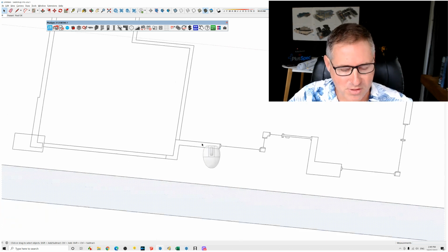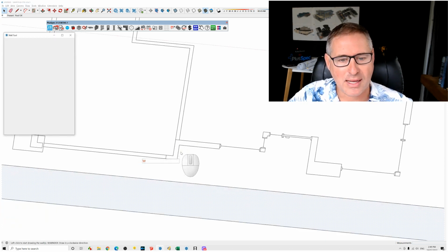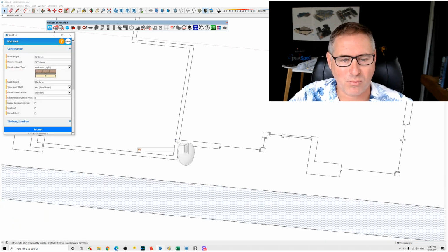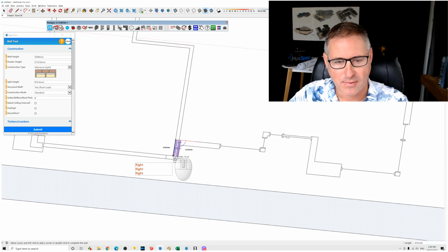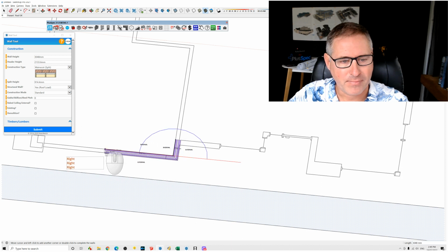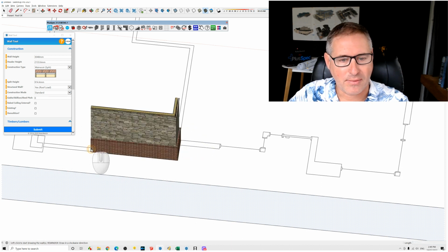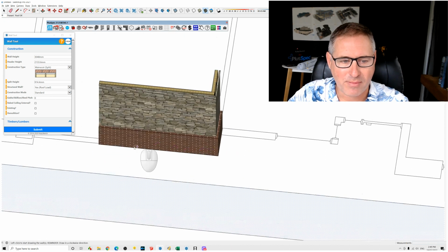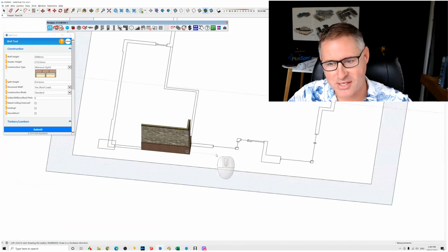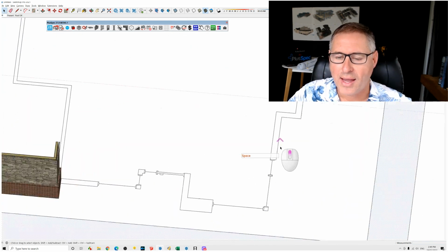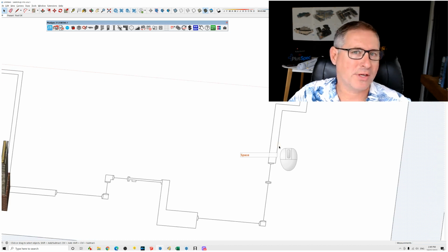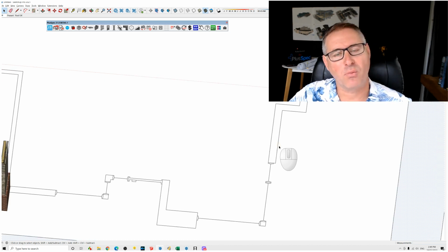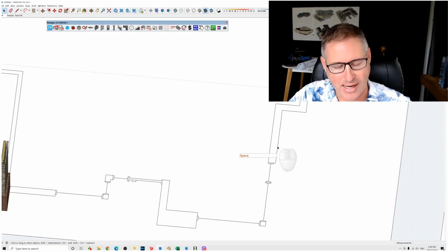The problem is that when he drew the wall, he was drawing it from the inside, right, which is not the load bearing point, right? I can do that. He drew from here, right? Now, when drawing from here, I'm now outside of my boundary. So the consideration to do is, instead of what's the overall thickness of the wall, what's the thickness of the wall outside of the load bearing point? And in that case, you would actually design in further.